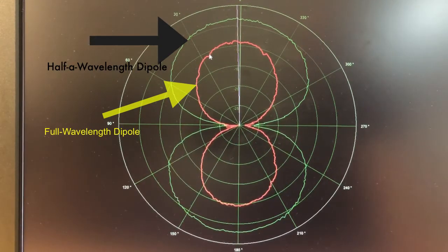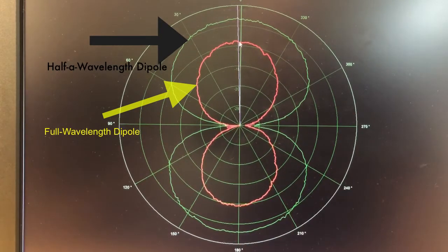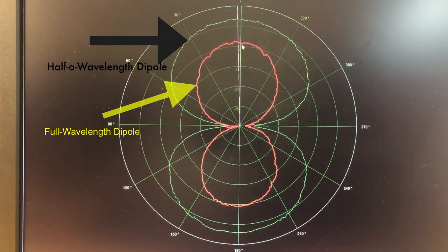The length of the antenna is larger for the 1 full wavelength dipole antenna. But on the other hand, the signal level is smaller than the half wavelength dipole antenna, almost in the order of 5-6 dB smaller, and that's counterintuitive based on the fact that we know that the directivity of the 1 lambda dipole antenna is larger than the directivity of the half wavelength dipole antenna.